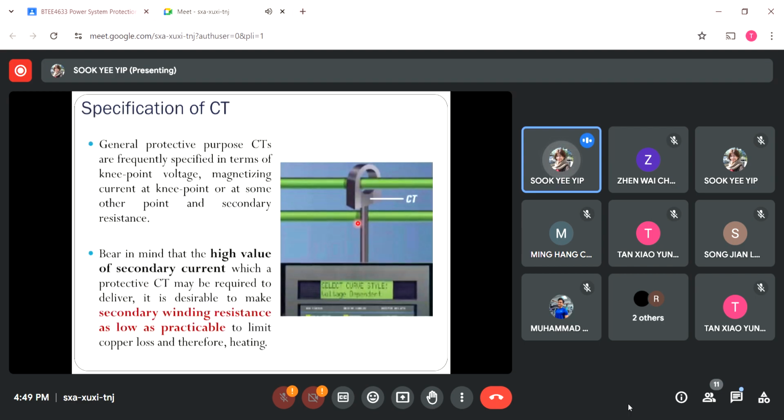All right, so the rules of thumb regarding the correct operation of a current transformer: remember, this current transformer should not turn into saturation mode. So we have to keep the secondary voltage at its output terminals from exceeding the knee point voltage value. And this knee point voltage we can obtain from the magnetization curve, remember? And what else we need to make sure is that the magnetizing current here should be as small as possible so that it will not cause measurement errors from the current transformer.